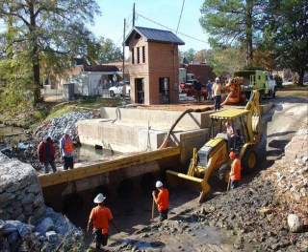And in Columbus we've had events that have topped that gabion wall you see to the right, and it's gone over the ground on the other end. But it pretty much acts like we had to do a HEC-RAS model that shows that we have no rise or boundary change in the 100-year flood elevation.